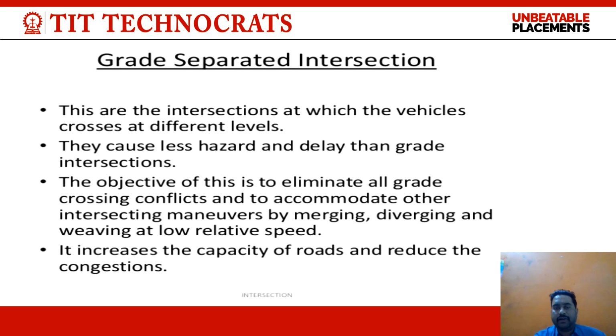Grade separated intersection. What do you mean by grade separated intersection? These are the intersections at which the vehicles cross at different levels. They cause less hazard and delay than at grade intersections. The objective is to eliminate all grade crossing conflicts and to accommodate other intersecting maneuvers by merging, diverging and weaving at low relative speed. It increases the capacity of roads and reduces congestion.